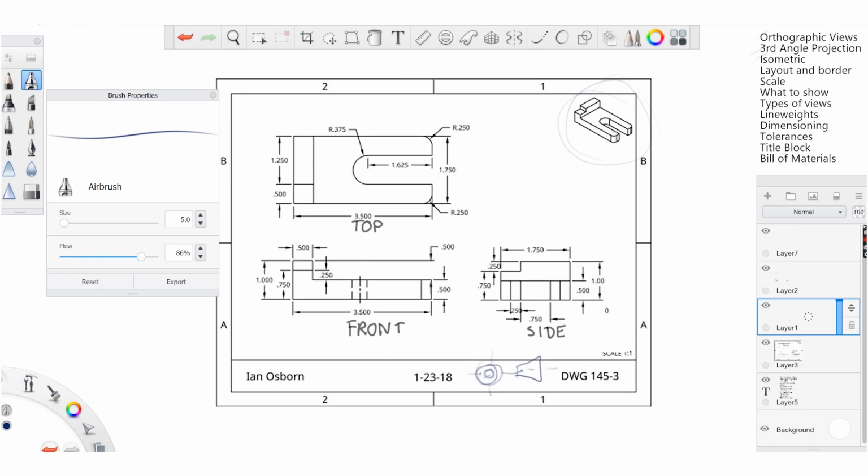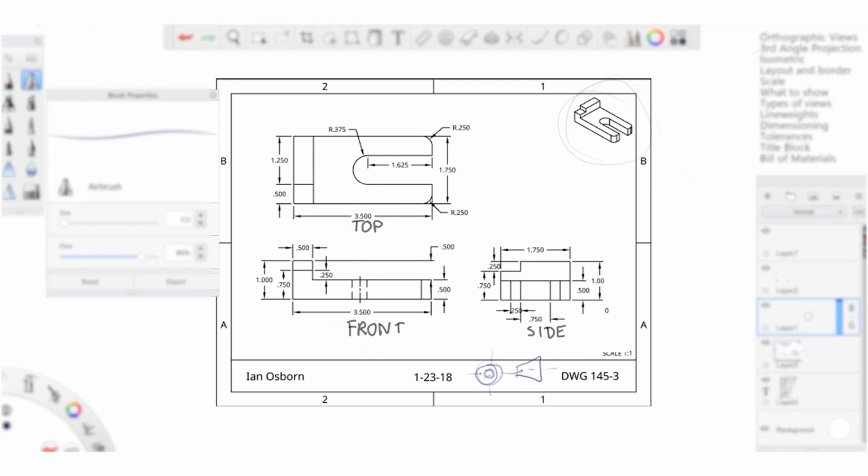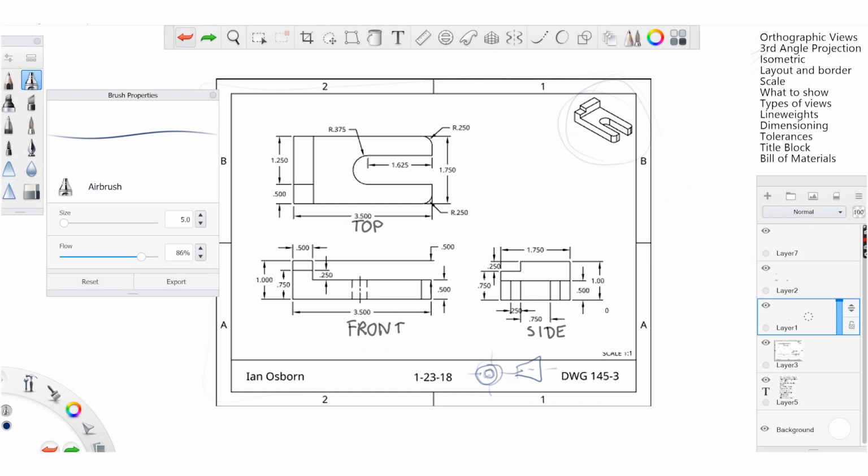In terms of layout, we will always have a border around our final technical drawings. This is a very, very useful tool, both for framing your product and exactly what you're drawing, to make sure that people don't think that there are missing views or anything like that you haven't included, and also for reference if you do have a really big page and need to reference a specific view.